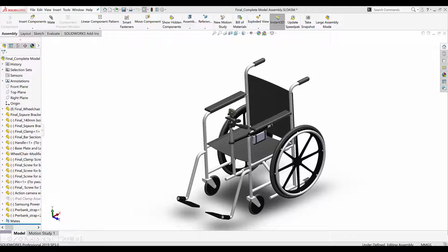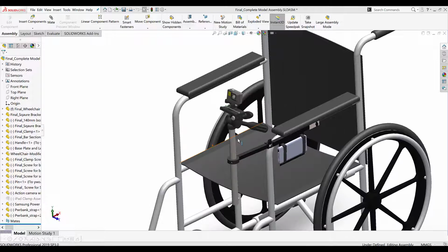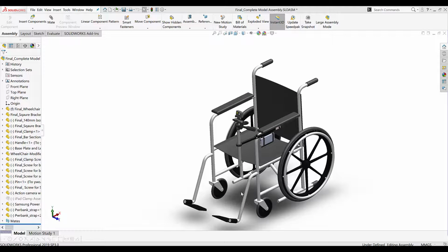So we designed this camera attachment for their wheelchair. So the wheelchair and the tripod sections and the camera, they're all downloaded from the internet, and it's only this black section here which was custom fabricated for the client. All these models weren't dimensionally accurate, so during the site visit, the wheelchair dimensions were taken along with the tripod. So the tripod, we had one in the office which we wanted to use, and we just took all the measurements from that and adjusted the CAD models which we downloaded accordingly. So we have a dimensionally accurate digital model.